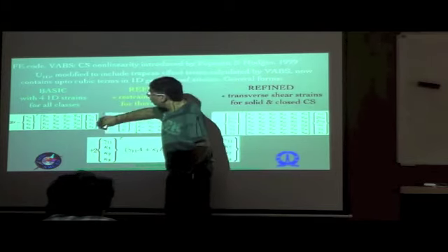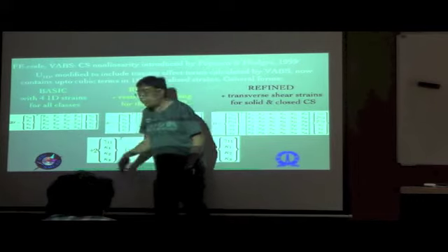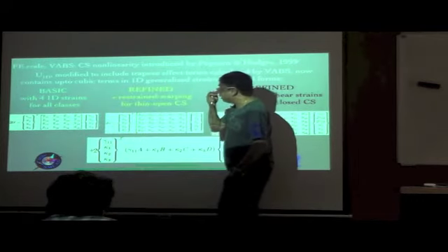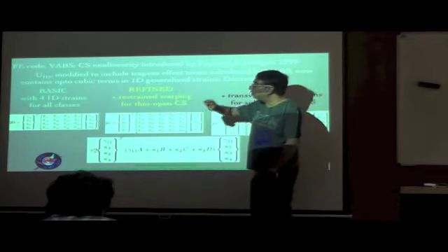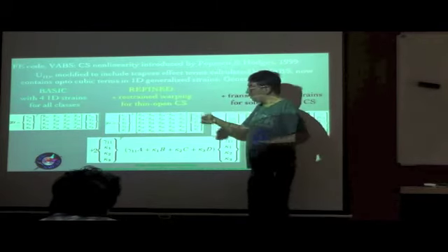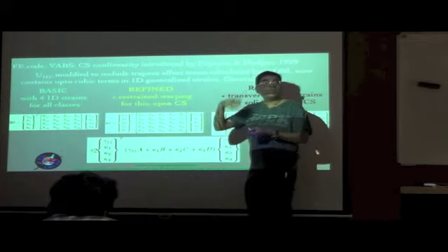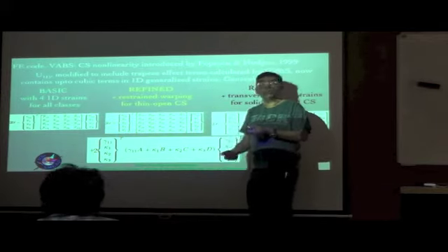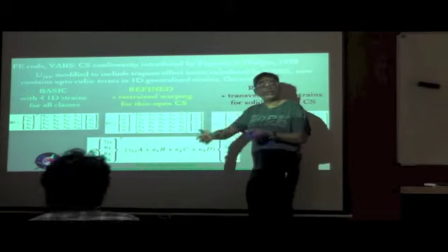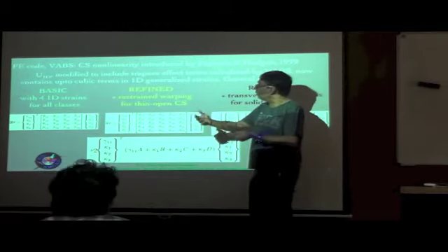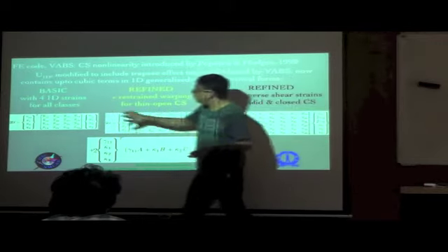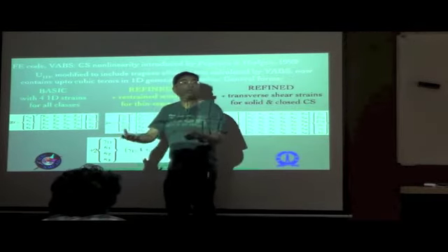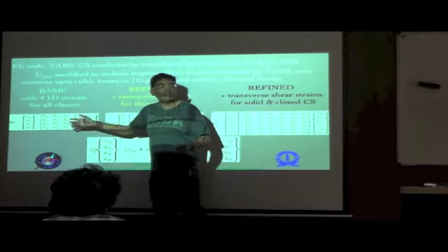So in such a situation, you have just a 4x4 matrix there with 4 1D strains for all the classes, and that's something which is valid for all classes. In other words, whether it is a solid cross section, a thin-walled open cross section, or a strip, in all such situations, the classical theory of the zeroth order approximation is basically this.